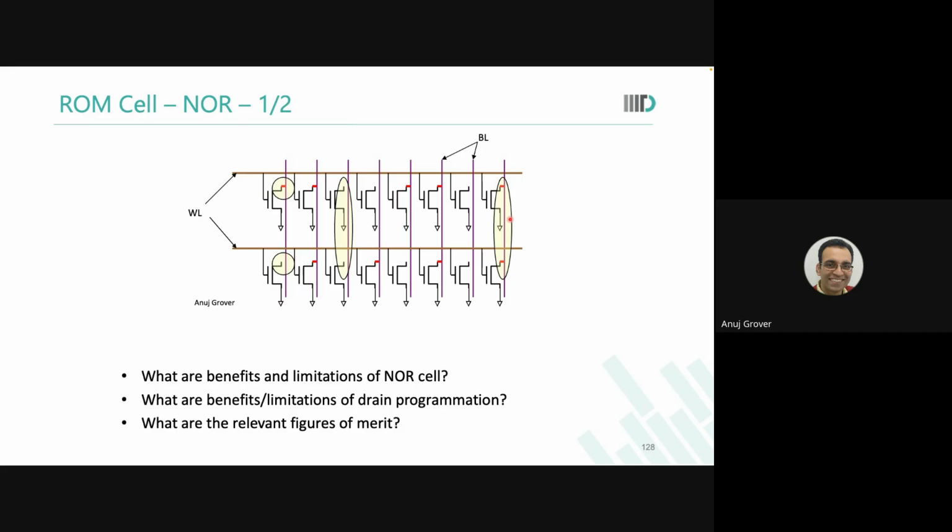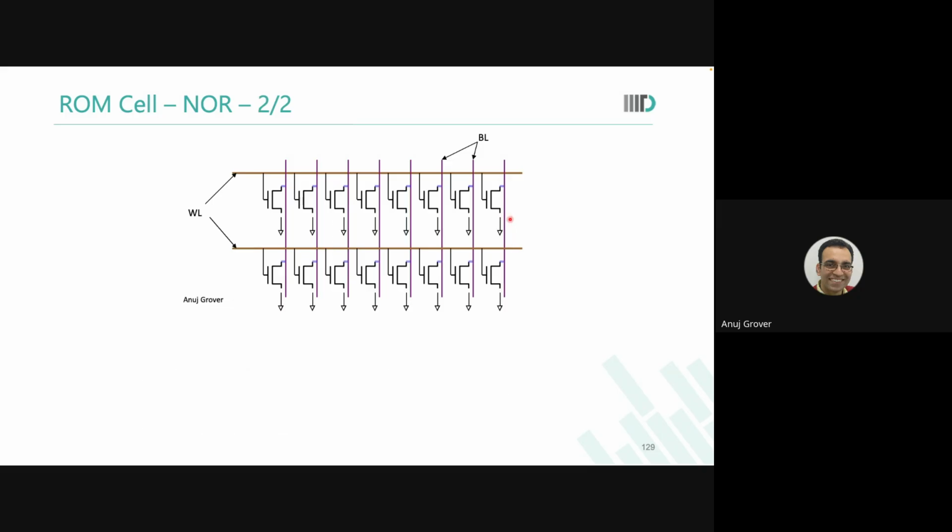So what you do then is that, instead of, so look there, what had we done there? We had left this node floating. Over here, what we've done, we have left the ground side unprogrammed. Wherever you want to store a 0, you put a connection there. Now again, this could be via 1, metal 1, contact, whichever way.